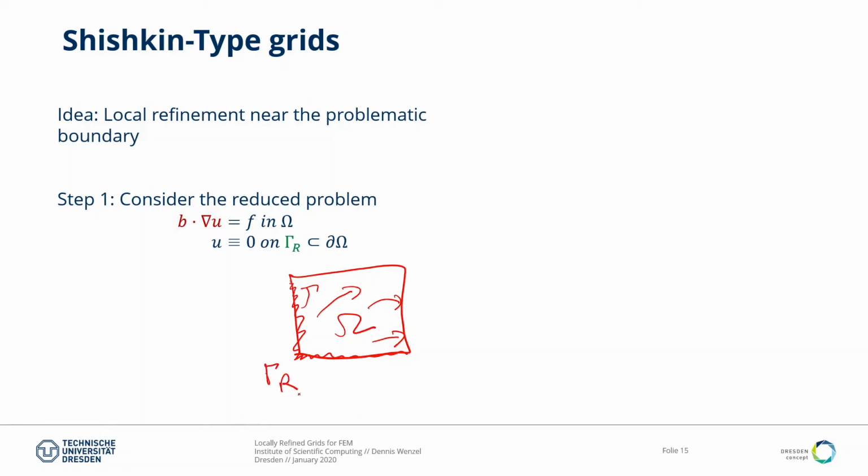The reason is that if you look at the solution behavior, when you have a convection, it always pushes the quantity in a certain direction, so in this corner up here, and that causes the stiff behavior and the strong descent of the solution close to this boundary. That's why, rule of thumb, choose the side of the domain where the wind is coming from, so to say.